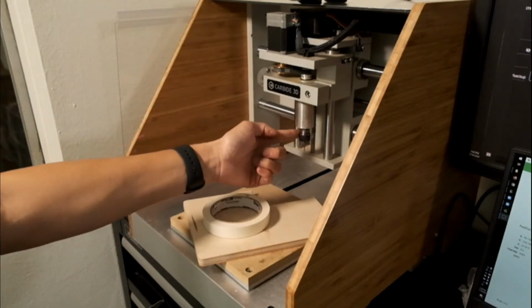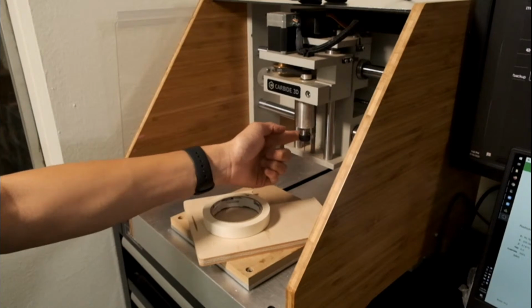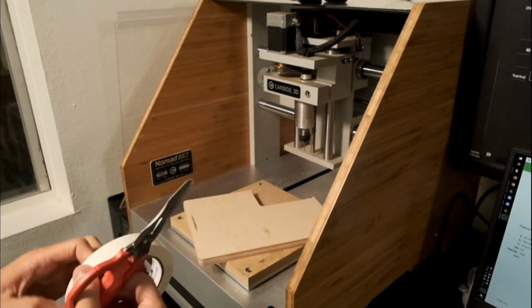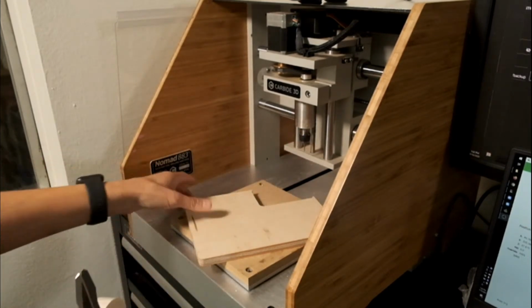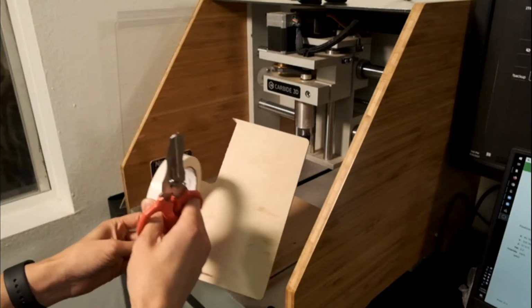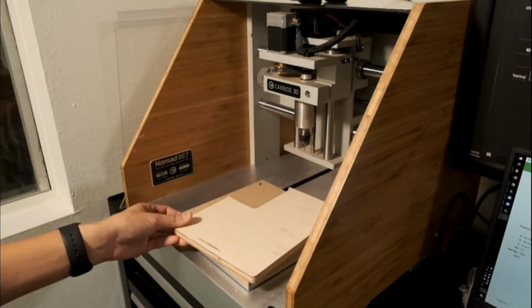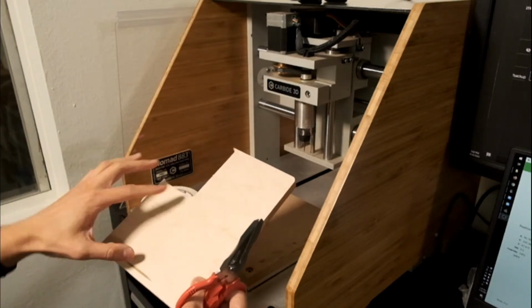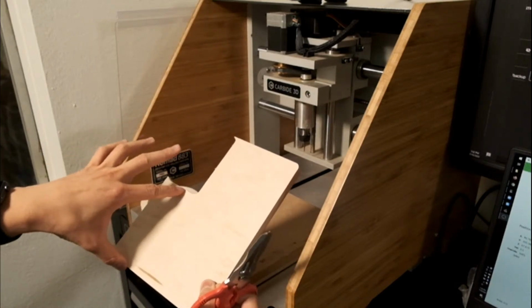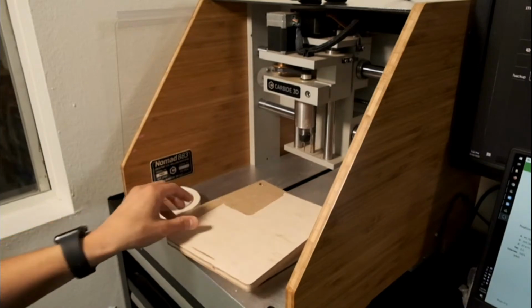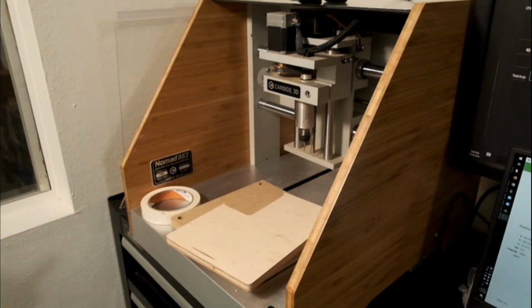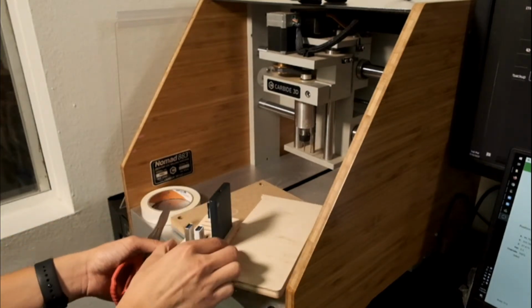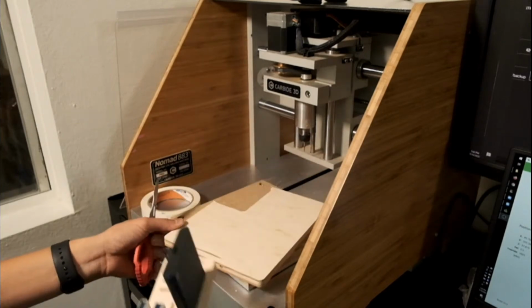And I already got the 1/16 inch end mill loaded up. So I know what the footprint of my part's going to be. I like to just cut in the lower left corner just to make this sort of symmetrical and just use up this stock. Let me make sure that this piece will fit. So yes, plenty of room.